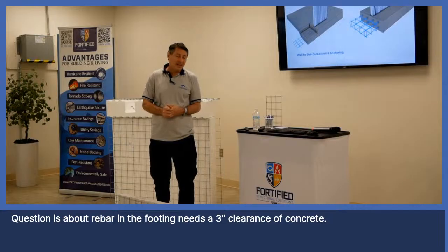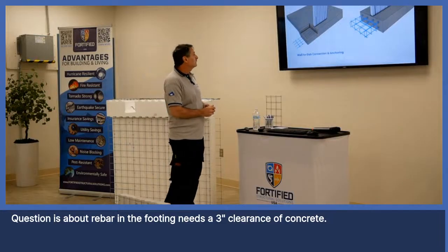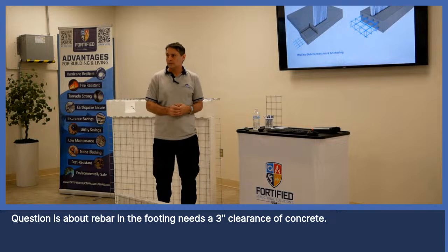I'm sorry, I don't fully understand that. Are you saying the slab doesn't come out far enough, and you're putting the rebar in about an inch away from the edge of the slab going down? We just have to maintain the clearance of the rebar in the concrete, 3 inches against it.